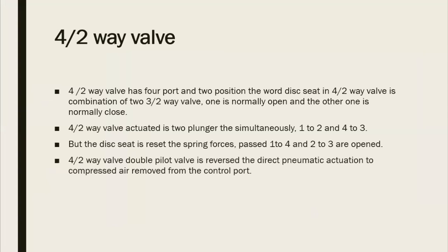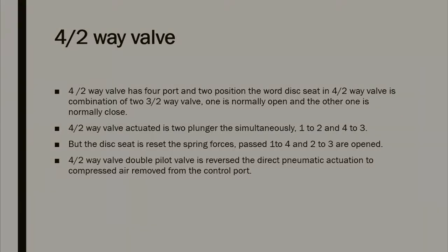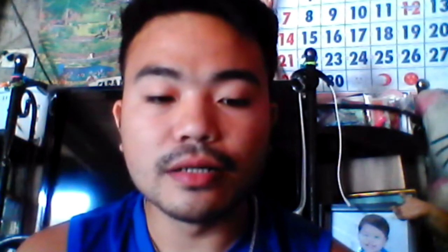For controlling a double acting cylinder, the longitudinal slide valve has a control piston for the reversal of the valve. However, the lines are interconnected or separated from one another by means of an additional slide.